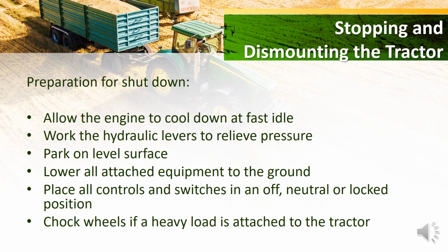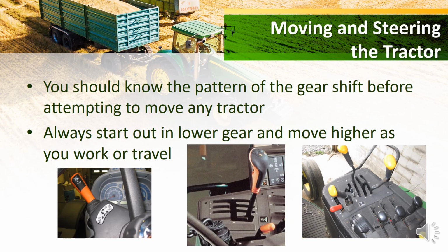So when you're stopping or dismounting a tractor, prepare for shutdown. Allow the engine to cool at a fast idle. Work the hydraulic levers to relieve pressure. Park on a level surface. Lower all of your equipment to the ground. Place all controls and switches in an off, neutral, or locked position, and chock the wheels if a heavy load is attached to the tractor.